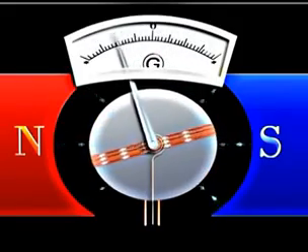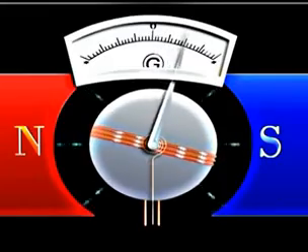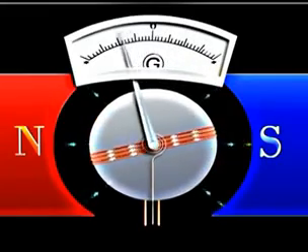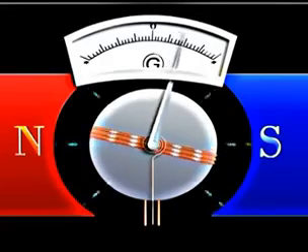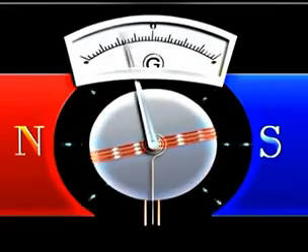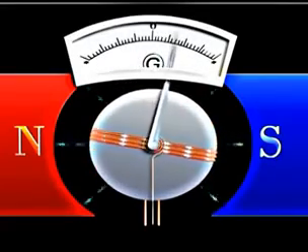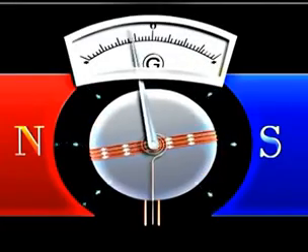When a current passes through the coil, it experiences a deflecting torque. The deflection of the coil is proportional to the current through the coil. A pointer attached to the frame moves over a scale which has been calibrated by first passing known currents.